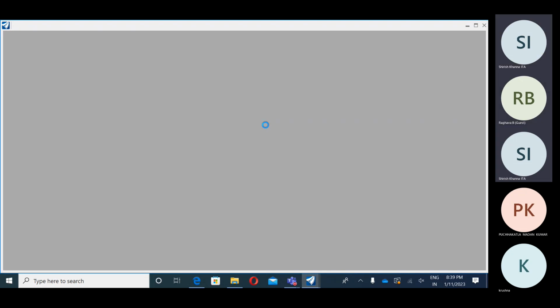Now, today we are going to start from the beginning. First we need some data. The data means we have data in different formats, like a text file, an Excel file, a CAD file, or a DGN file. So we have very different kinds of data that we can open. Today we are opening a DGN file, and we are going to analyze that data first. Which kind of data we have, how many points are there, how many contours are there. We have to check the data first, so that we can create the alignments over that data. We have to combine that data with a 3D surface, with that geometry, horizontal alignment with the 3D surface, and then we can create the vertical alignment too. So these are what we are going to learn.